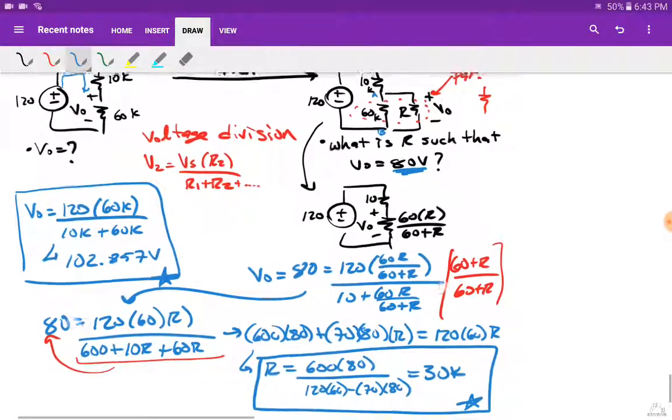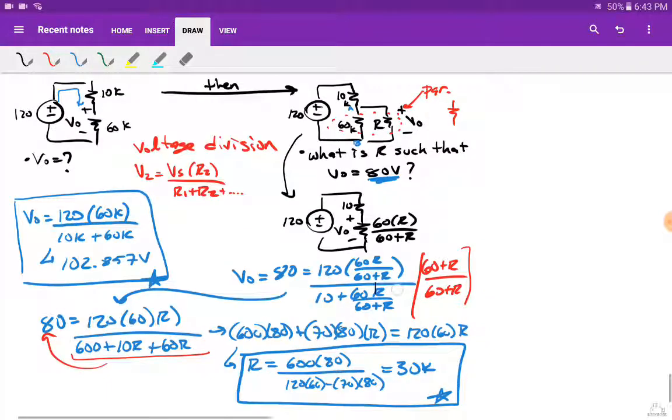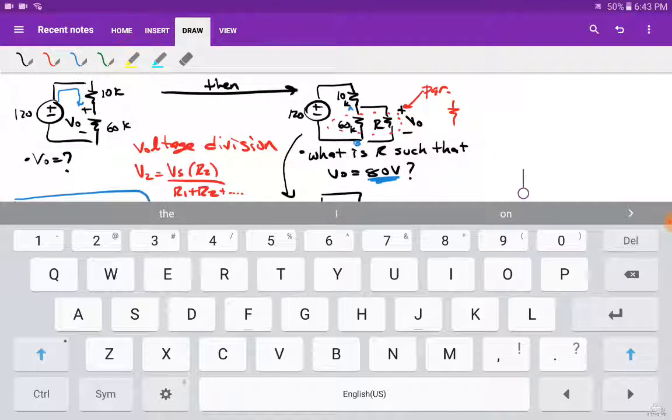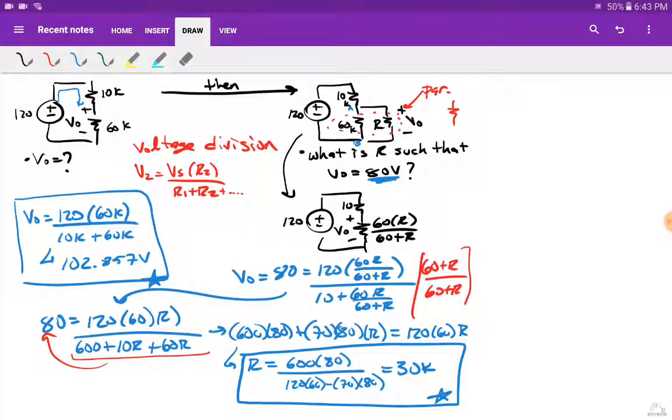It's no different. Once you recognize the fundamental situation, then you handle it just like it were fundamental. So once I recognize, oh, I see a voltage division, I see basically a parallel connection inside of a voltage division. Once I see that, I draw my voltage division with the parallel connection inside, and I can solve it. All right, pops right on out.